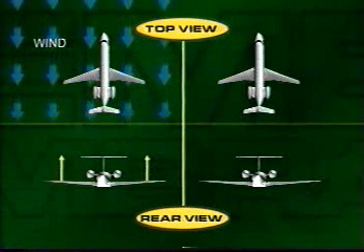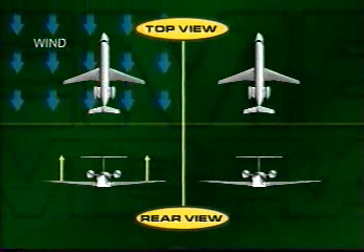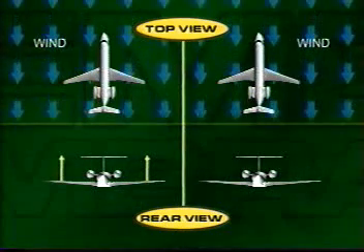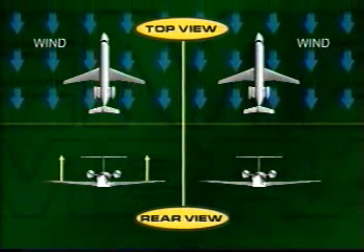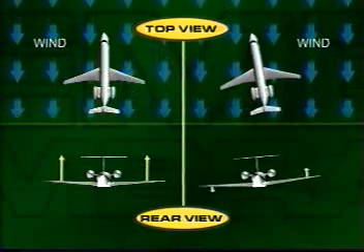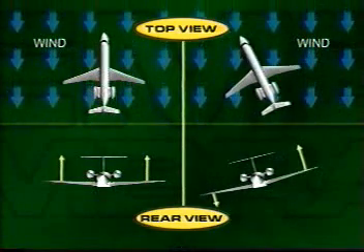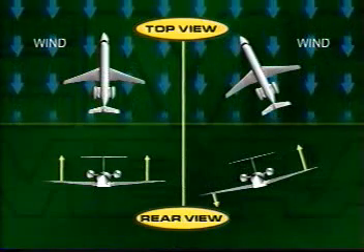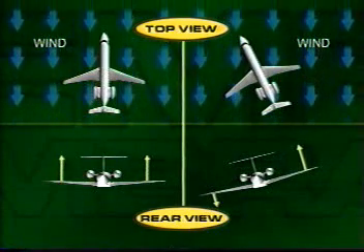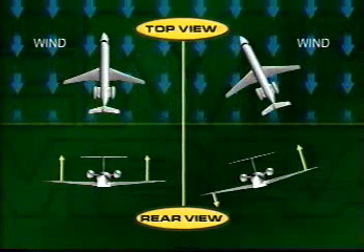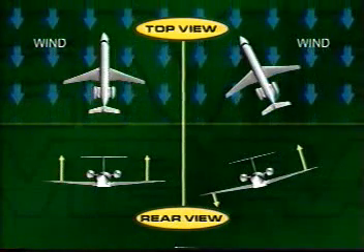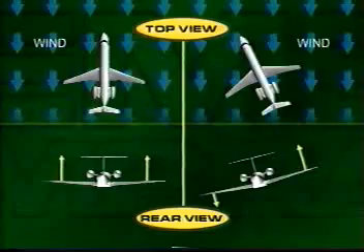When the aircraft is yawed, the inside wing is slowed down, and the outside wing is speeded up, therefore unbalancing lift in each wing separately, resulting in aircraft roll. The outside wing produces more lift because it is effectively less swept, while the inside wing loses lift because it is more swept. This contributes to further unbalanced lift, and rolling is exacerbated markedly, adding to the actual geometric dihedral.